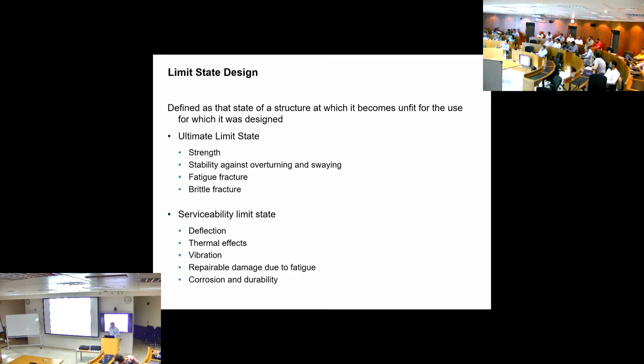When we design, you send us the documents and we design the project. We usually consider the possibly walkable area, like the walkway or the periphery, and we put hard insulation there without you asking for it, because it is part of the standard practice we do. So where you may walk, we consider, but definitely you should not walk in the pan. You need to walk on the seams, because the seams are the ones that take the span in the middle.